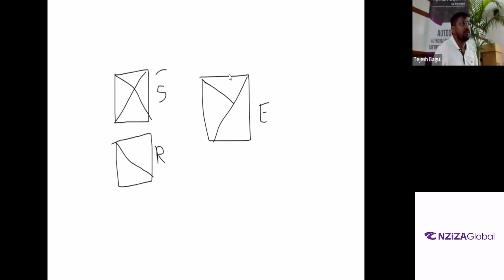Now, Y, X, and just a slash. Many a times, this symbol is also used for outside air. But make sure you have the tag properly assigned to it. Whenever you are drawing tags, make sure you have the proper outside air tag assigned to it. We don't want confusion about whether this is a supplier or an outside air duct. All right. Going back to the presentation.